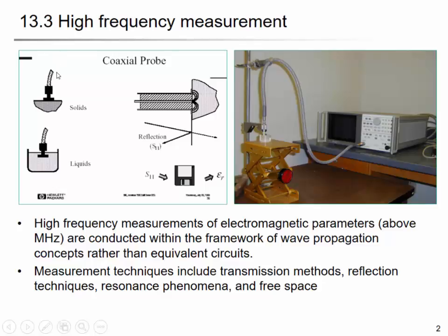So if you connect this probe to the electronics, like the high frequency impedance analyzer, then this emits a sinusoidal wave, and then it detects the reflective wave from the specimen. Okay. And the penetration depth of the wave generated is only in the order of a few millimeters, so it can reflect the property in that local area.